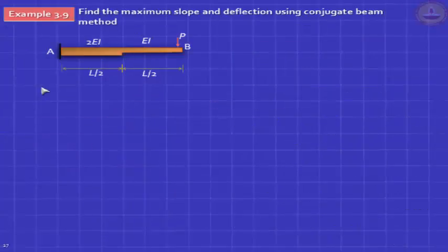Okay, here's an interesting problem where you have a changing EI. This is a stepped beam. It's a non-prismatic beam, but fortunately, you could have a tapered section, making it more complicated, but we have a stepped section. So one half of the beam has an EI which is 2 times the other half. Does it mean the depth is 2 times? No, not necessary. If the cross section is rectangular, I goes up with the cube of the depth. So you need not have the depth 2 times to get this.